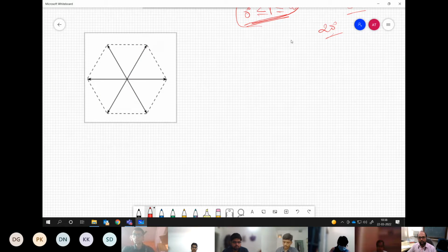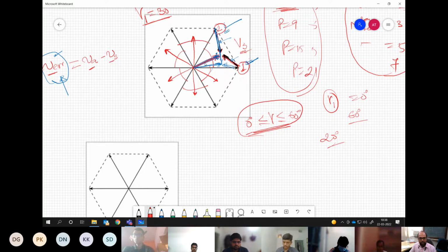So the first thing you also realize over here is: what is the angle between each sample? What is this angle? 60 degrees. This is also called the sampling angle or sampling interval, because time and angle are related through omega. So gamma sample means that these vectors repeat at every angle gamma sample. And how much is that? It is basically 60 degrees divided by the number of samples, right? So for P equals 3, or n sample, you can directly write it over here.